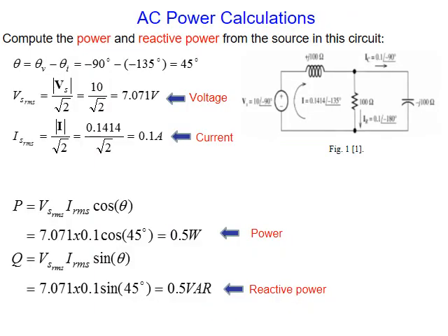Okay. Now after that we go to find the power. We mentioned in Module 1 that the power, and we are talking about single phase here, is VRMS times IRMS times cosine of the angle between them, which we already have. This is VRMS, this is IRMS, and this is the phase shift we already calculated. So this is the power. Which power? What do we call it? Power could be called general power. Sometimes we call it active power, or let me say real power.